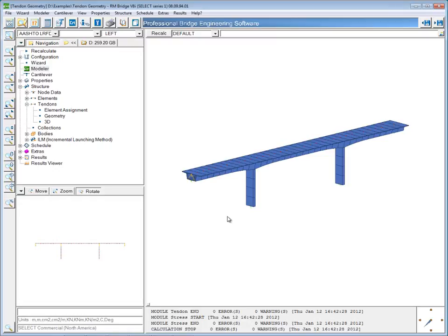In the previous two methods, the tendon geometry was defined by changing the point through which a tendon profile was referenced. So in method 2, the tendon was defined as passing through different points along the length of the bridge. And in method 1, the tendon was referenced to different points, one at the top and one at the bottom of the section.